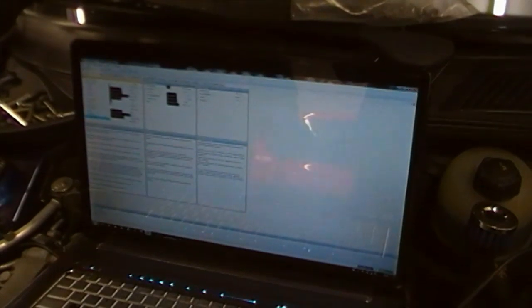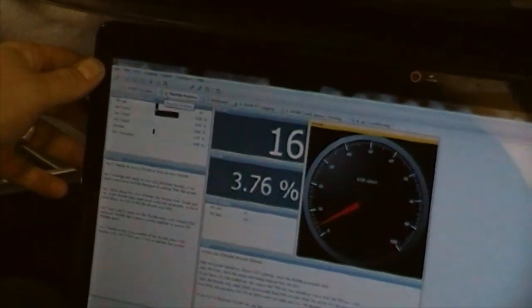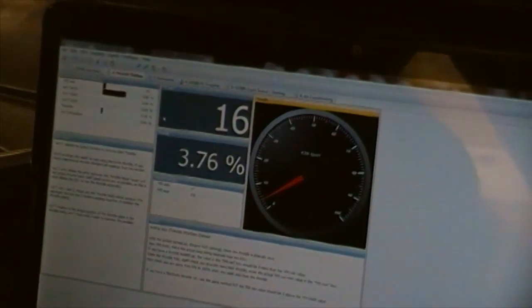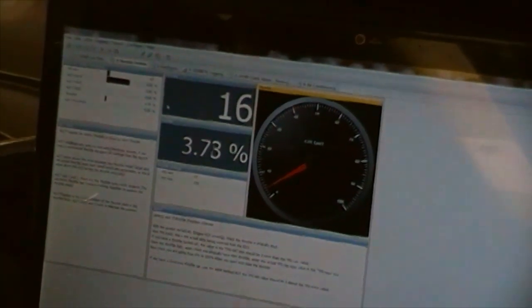Okay, now we've connected into the ECU and we've got everything operational in that respect, we need to set up the throttle position sensor which we've previously fitted. Now this is still loose, so you can rotate it into its start position. So what we need to do is go to the throttle position tab in the software, click on that, and you can see the value here, TPS raw, that is showing us the base value of the throttle position sensor.